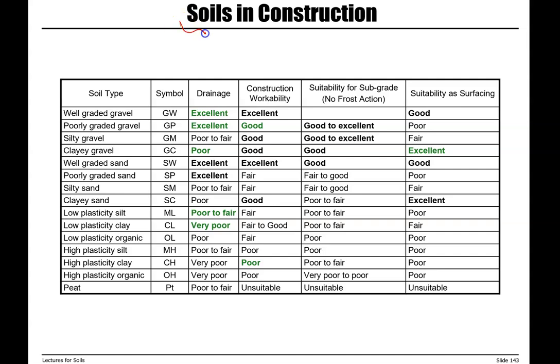You can see different soil types, the symbol, which one has a higher or better drainage, which one is a better option with respect to workability, which type of soil is suitable for subgrade application, and which one is more suitable for surfacing.